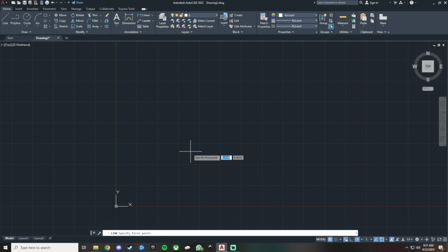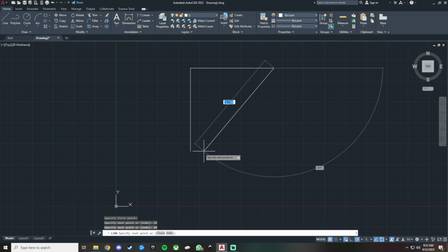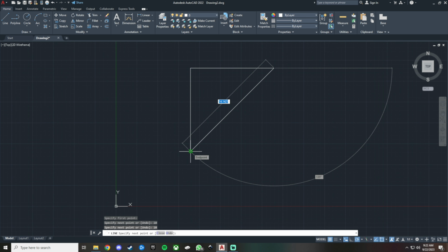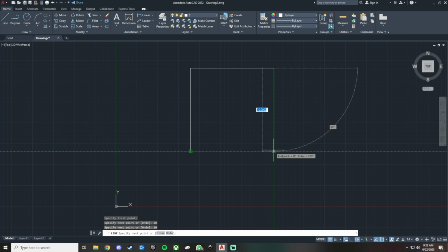Let's draw a square. We're going to make it 10 long by 10 wide, obviously, because it's a square. So 10 up and then 10 this side, and there we go. Something I do want to show you guys is that instead of having to press 10 in again, we can also just get to a snap point of the other line, because we know the other line is 10 millimeters. As you guys can see, when I move my cursor away, we now have this line and it's already snapping it for us. It's 10 millimeters long, so we can just click it.